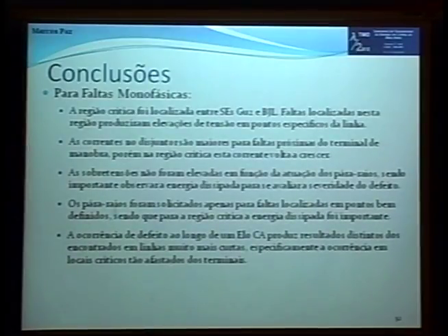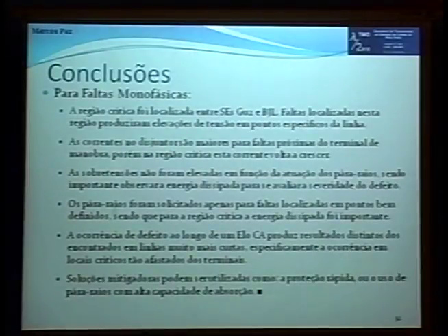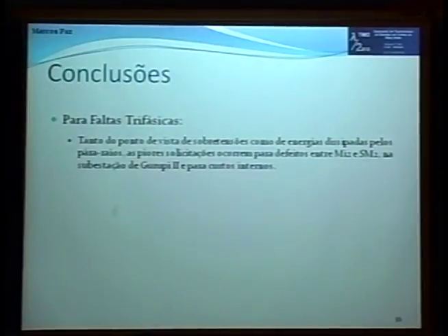And this was observed specifically due to the work of the surge arresters located further away from the fault point. Possible solutions for a single-phase fault would be the use of fast protection or the use of surge arresters with a higher capacity of energy absorption.